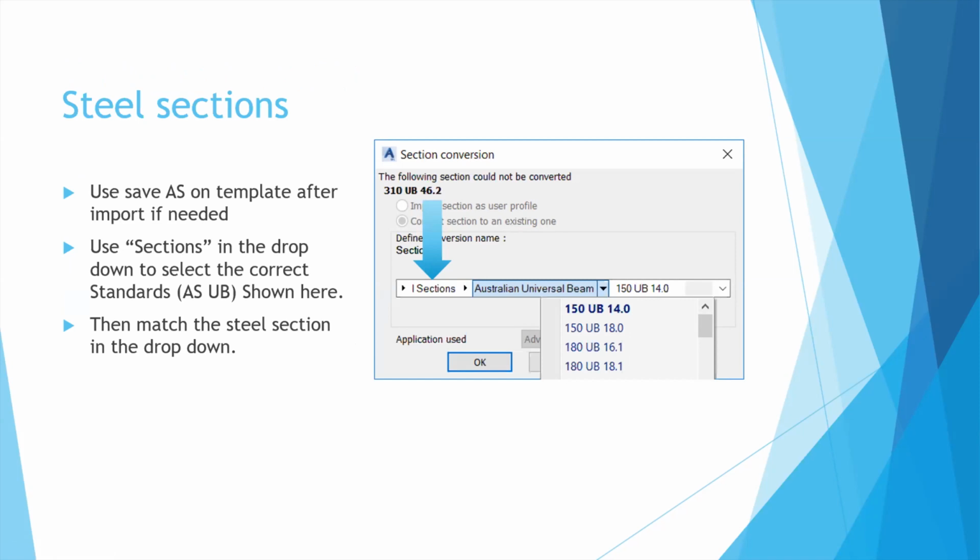So what it's trying to do, even though I've got an Australian steel loaded in Plant 3D and using it, in Advanced Steel, it still wants to map it, right? I don't even know why, for me it looks like apples for apples, but it still wants to map it. So we're going to have to deal with that for the moment until they improve things.